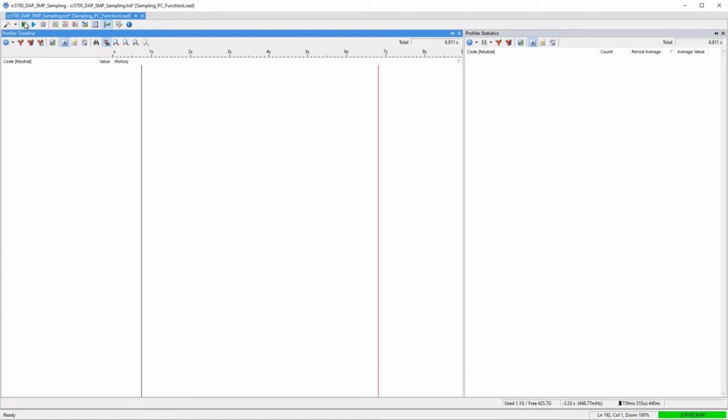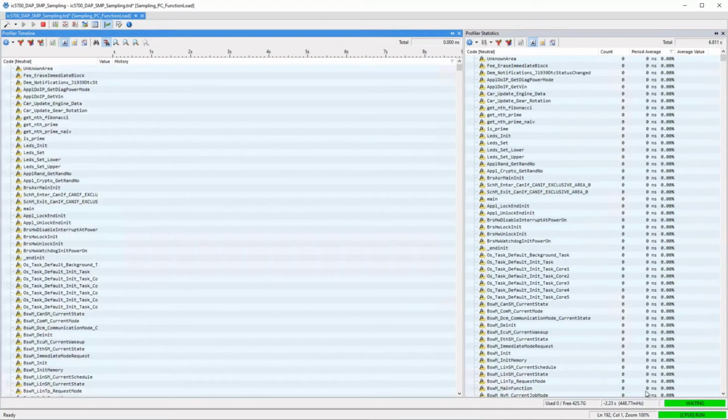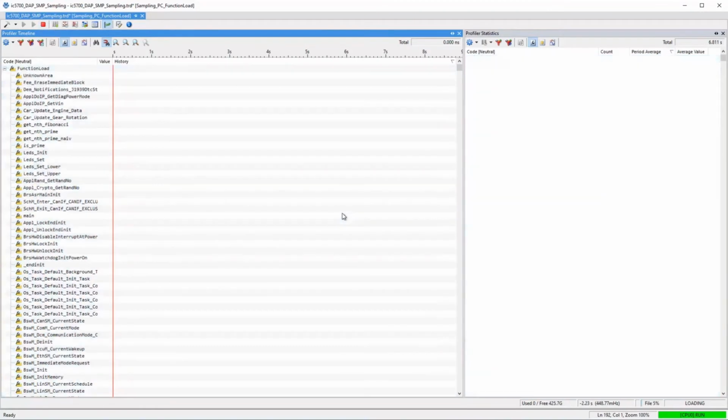So now we can just run the trace. The CPU is already running. We can see it's waiting here. I actually have a trigger set up at an end condition, so we will never meet that end condition, but it's recording the PC right now. So I can just stop it at any time, or if that end condition were to hit, we'd see the trigger and the trace would stop. I'll just stop it manually.